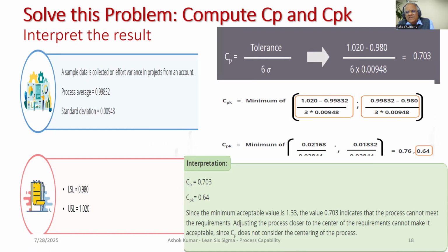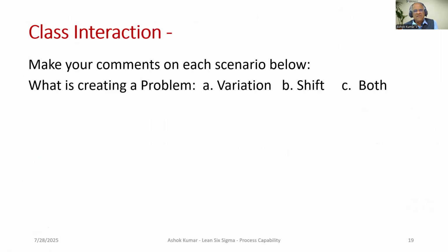So adjusting also doesn't help you to achieve an acceptable process. Considering only the inherent variability of the process, that is CP, it does not meet the closer-to-1 requirement. So your process can be concluded as definitely incapable, and you can launch your Lean Six Sigma project to identify the root causes, analyze the root cause first, then go to the possible solutions and implement them in your process. Is it clear now within the Lean Six Sigma DMAIC framework?